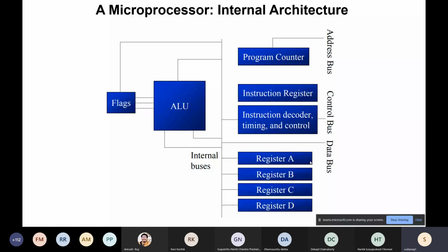It will go, there is no space here, there is no 9th bit here. So that 9th bit, whether it is carry equal to 1 or 0, that will come and sit in the flags. So flags is a type of bit addressable register or memory location, you can say. Bit addressable. So in register A or B or instruction register, all 8 bits are written or operated at a time. You cannot do bit after bit most of the time. Most of the time. Not always, I am saying. But most of the time, you have to deal with all 8 bits simultaneously.